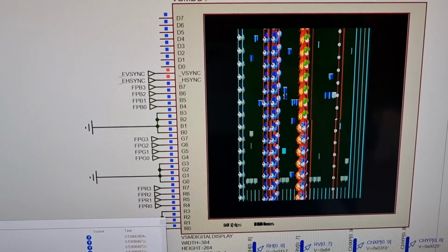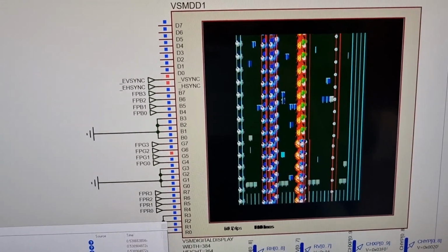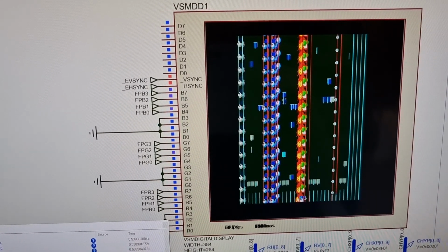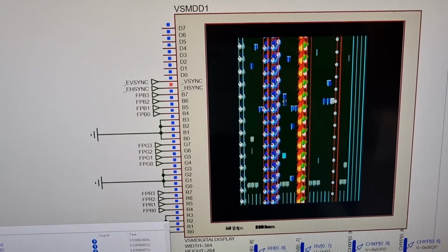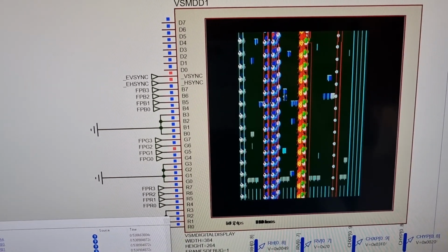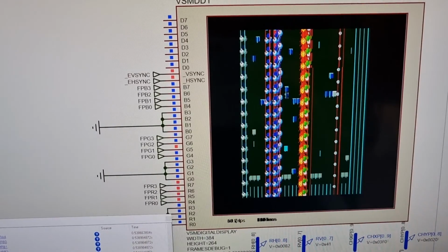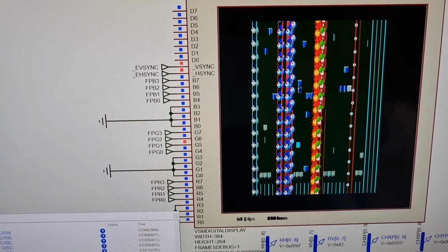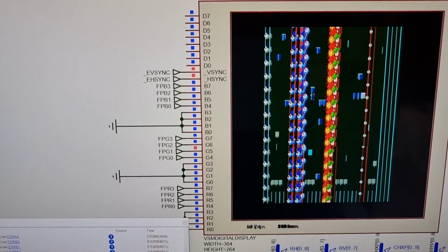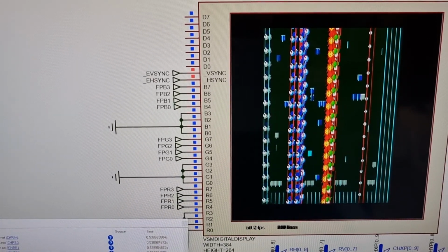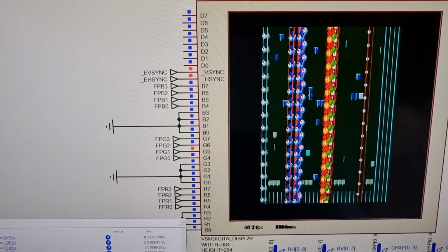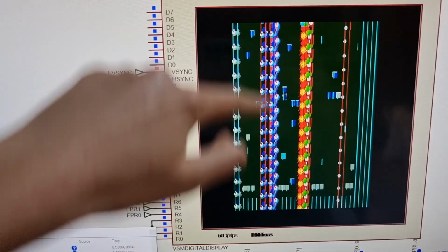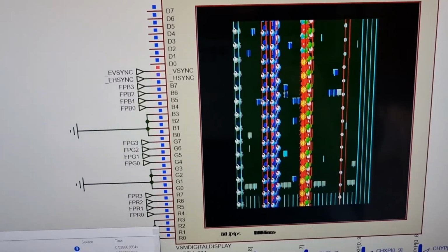Short debugging update. So one of the first solder bridges that I found was that U18 pin 11, plus 5 volts VCC, was connected to the nearby via, which was ED5, and this would cause data contention issues on practically the whole bus. Now when I try this in the simulation with the same data captured via the emulated user port, I can see the same vertical strips in the sprites.